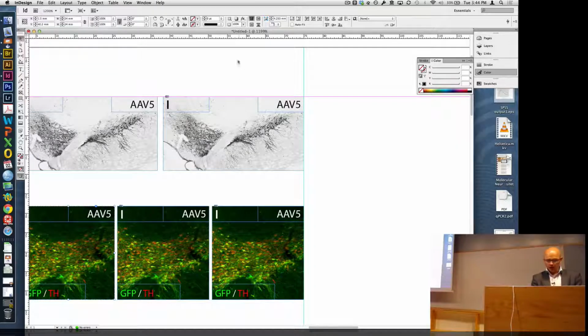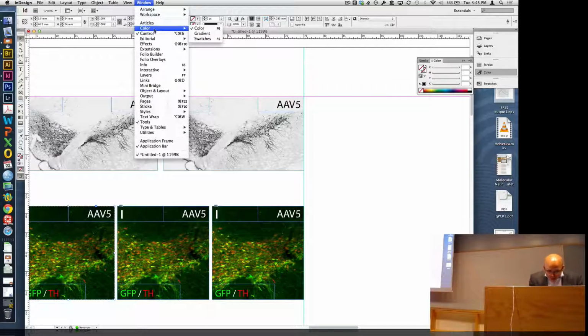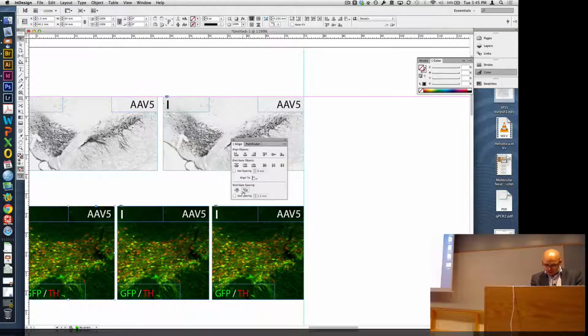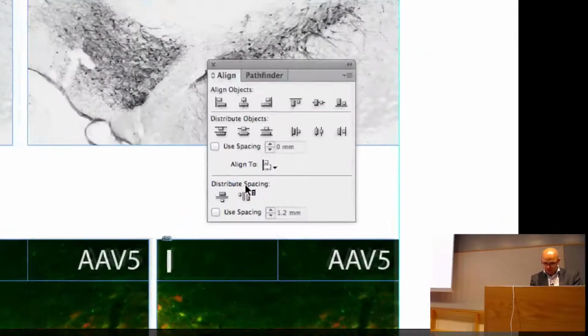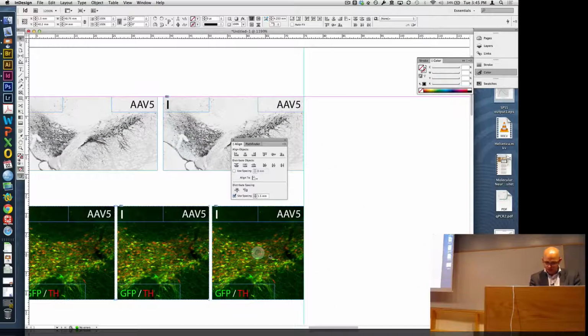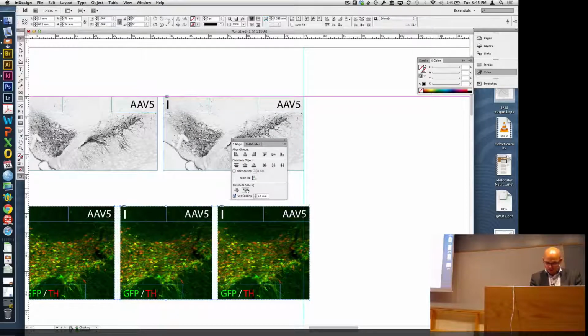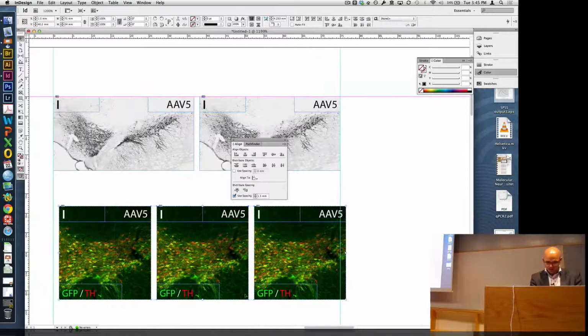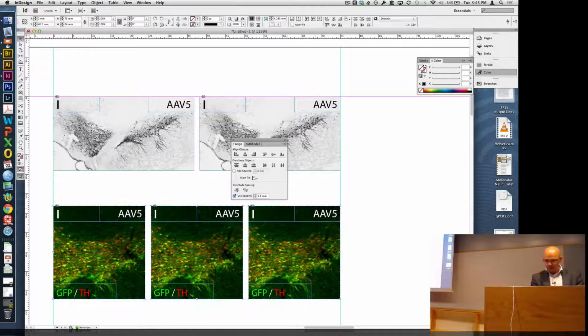And then you can utilize this align tool. So we have Windows, and you have Object and Layout, Align, and we can use the distribute. So here you can specify your spacing again, and we said that we wanted this to be 1.5 millimeters. And then you can just go in, select those 3, have them be distributed 1.5 millimeters. And if it's calculated correctly, these should be exactly 75 millimeters width. So that looks good. And then the same thing is in here.